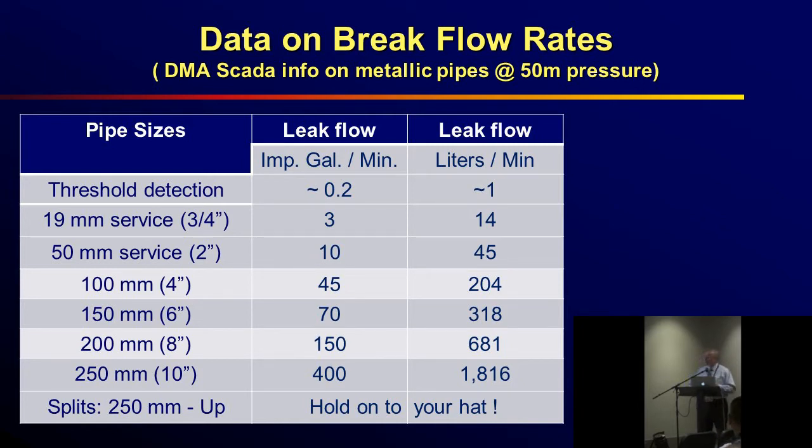And at the end of the day, this really is about the volume of water that's lost. We talk about leaks and flow rates, but at the end of the day, it's about the volume. And the volume is the flow rate times the run time, right? That's the key. We're going to spend some time on that today, about run time. This gives you a sense of the flow rates, and then it's the run time, and then we're talking about the volume of water that's lost.